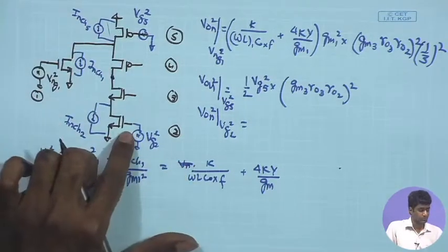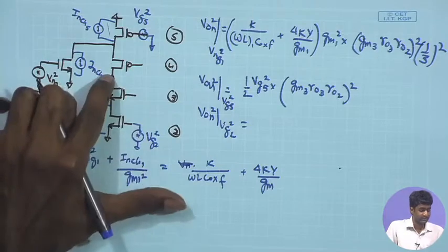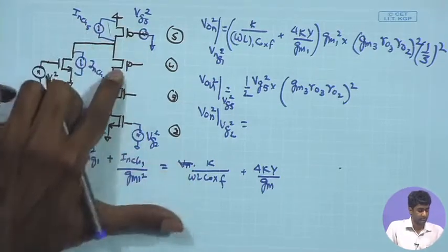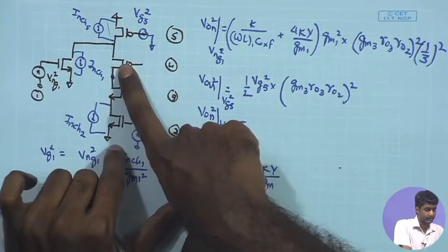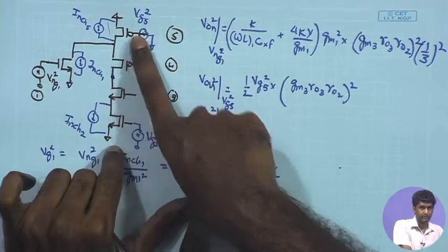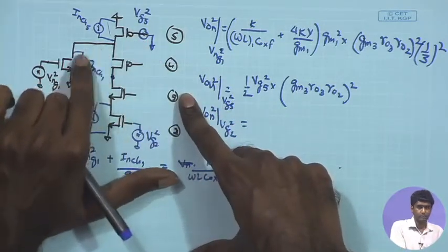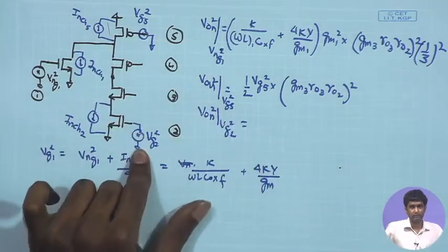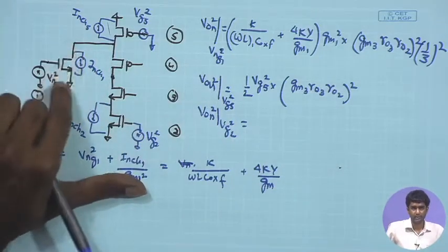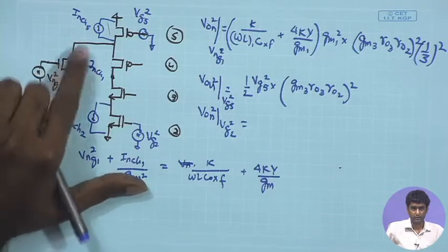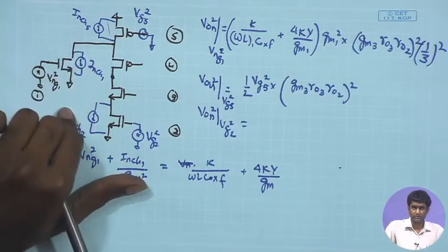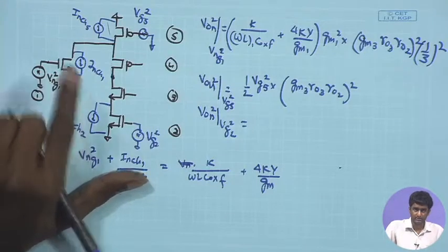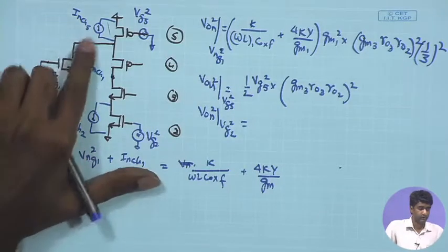So, for VG2 the expression for the gain from input to output is same as what we have from the VG5 to output. Only thing is in terms of the MOSFET, the impedance will be contributed by M3, M4 and M5. This node is again not going to contribute much, because when I am analyzing the effect of VG2, once again this MOSFET is going to represent an impedance of GM times RO square, because of the 2 stacked MOSFETs coming into picture. This is not an AC ground for that operation, and therefore, I can once again safely ignore this.